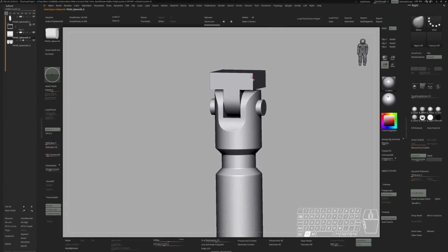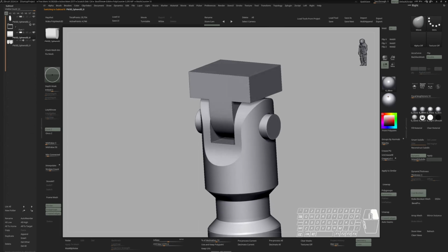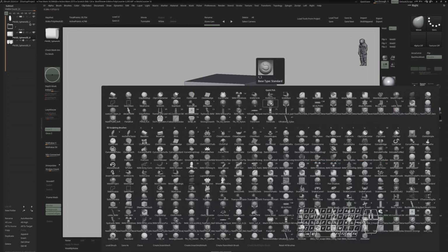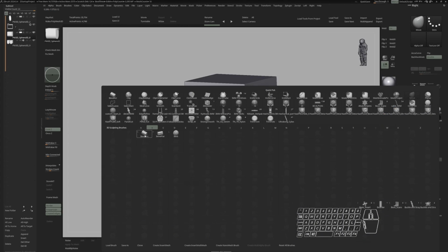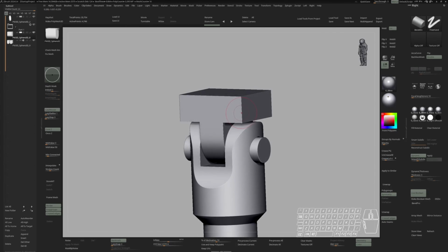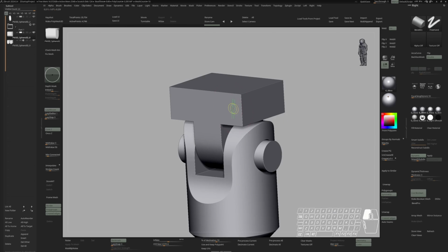And now I would like to create some thicker chamfers on this piece right here. And for that, I'm going to make use of the bevel brush. Press B and B again for the bevel arc. With this brush, you can click between two surfaces around an edge and just clip away that edge like so.